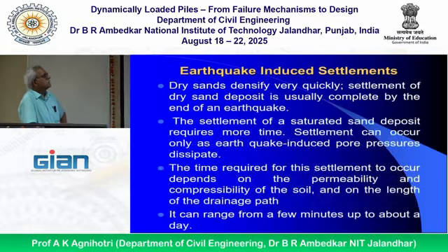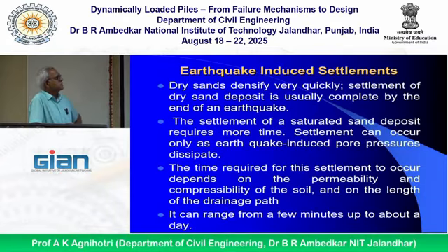Now, earthquake-induced settlement for dry sands. Dry sands densify very quickly. Settlement of dry sand deposit is usually complete by the end of an earthquake. And settlement of saturated sand deposit requires more time.